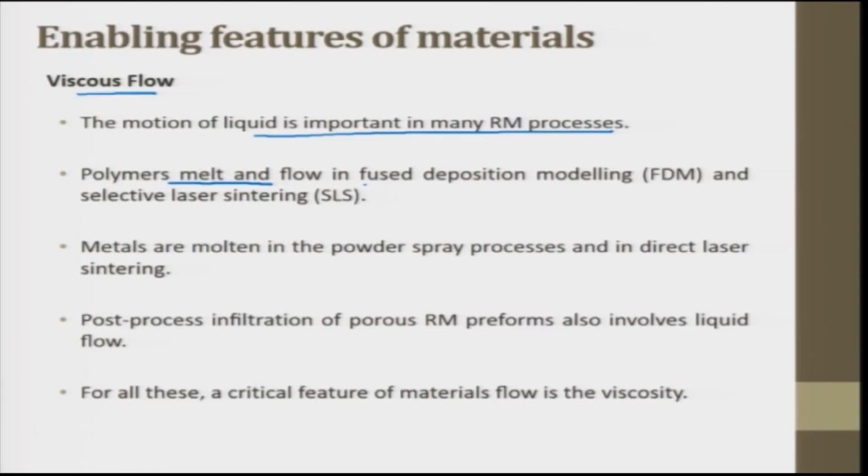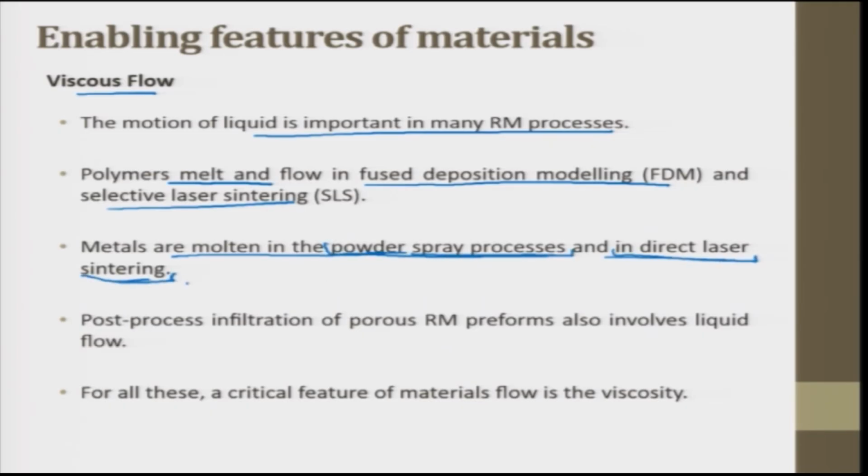So, polymers melt and flow in the FDM process, fused deposition modeling, and selective laser sintering. Metals are molten in powder spray processes and in direct laser sintering. Post-process infiltration of porous rapid manufacturing preforms also involves liquid flow. This is all regarding the liquid based processes, those we discussed. For all these, a critical feature of material flow is viscosity. So, viscosity becomes an important factor.